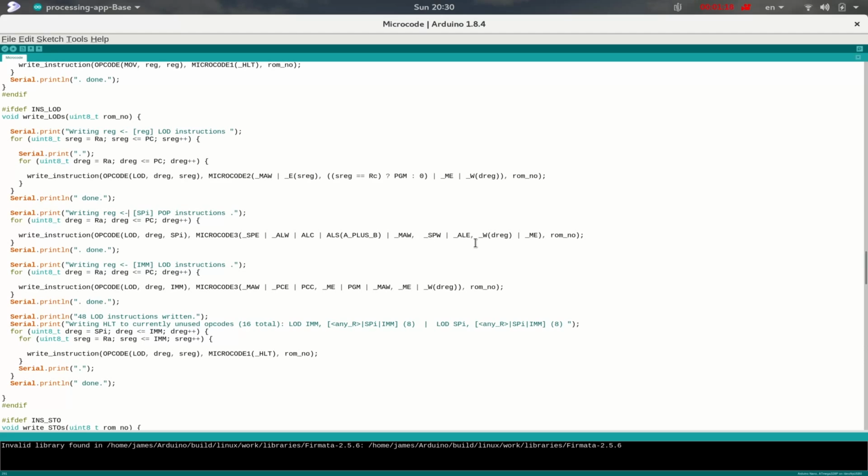And then we need 2 cycles to actually read out the data from memory and to write the new value of the stack pointer back into the stack pointer register. The order of these is somewhat arbitrary, and so we chose to first write the result of the ALU increase operation back into the stack pointer, and then on the last cycle we will read out the memory contents, which were located where the stack pointer was pointing at the beginning of the instruction, into whatever register we want to pop our data into.